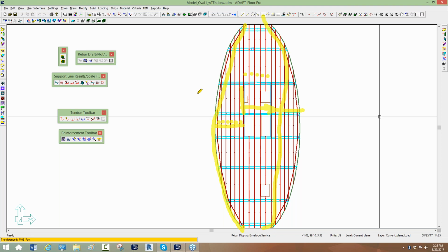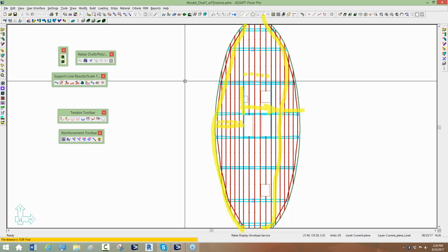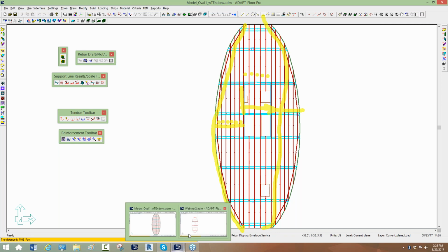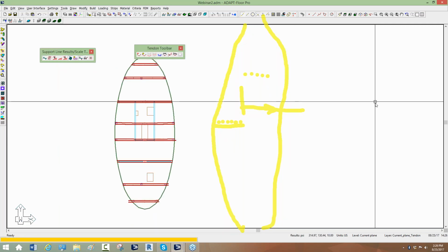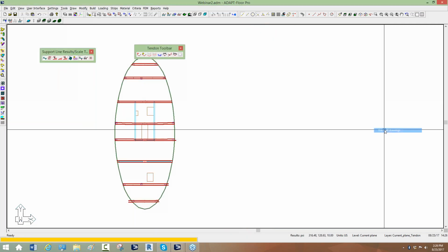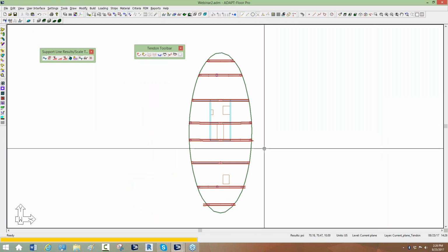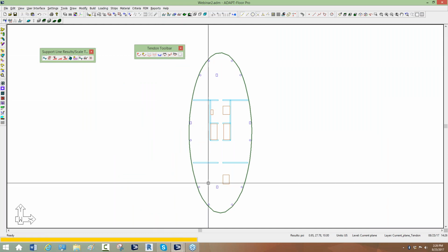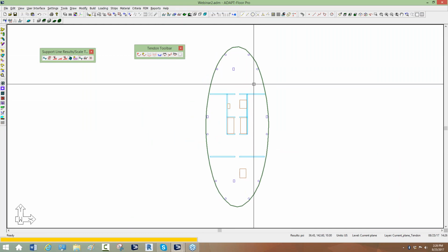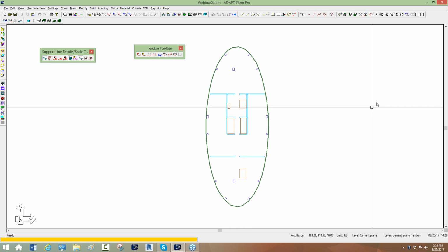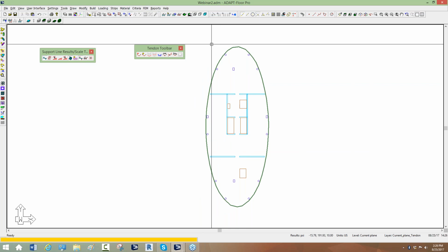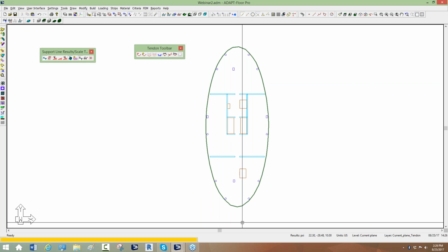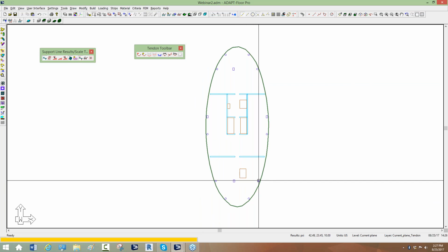Now, an alternate way, again, as I mentioned earlier, was to use banded. So in order to do that, we have to generate design strips for the uniform direction. Now, typically, the support lines for banded directions will follow the actual flow and the location of supports.